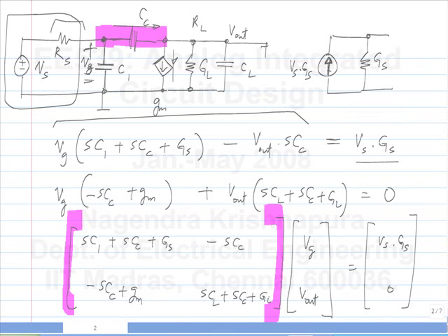if you have some voltage at this point, there is some current in phase with the voltage through the GM, and there is some current 90 degrees from the voltage through CC. Because of this, you get a zero. You get an out of phase addition. So if you have increasing CC, the part of the current through the capacitor increases, so the frequency at which it becomes significant moves lower.